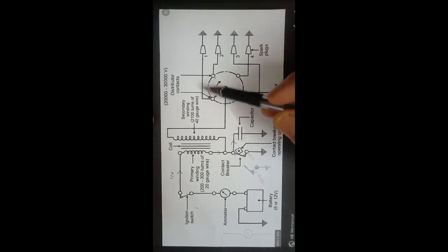So this also demands frequent maintenance, as well as causing wear and tear of this particular system. Performance will also drop when there is a deposition of carbon. The health of the spark goes on reducing after running the vehicle a few thousand kilometers due to deposition of carbon. So these are the drawbacks of the conventional ignition system.